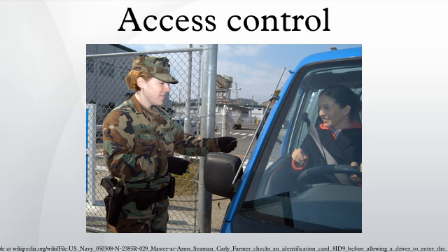Disadvantages: operation of the system is highly dependent on main controllers. In case one of the main controllers fails, events from its subcontrollers are not retrieved, and functions that require interaction between subcontrollers stop working. Some models of subcontrollers do not have the memory or processing power to make access decisions independently. If the main controller fails, subcontrollers change to degraded mode in which doors are either completely locked or unlocked, and no events are recorded.